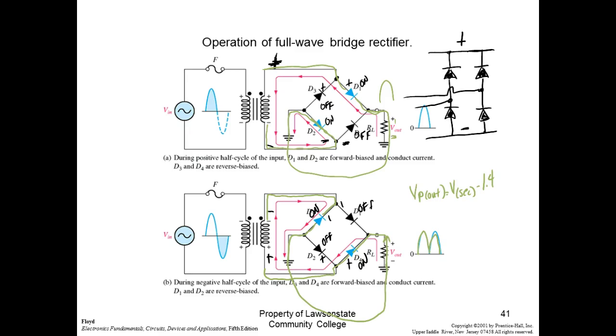So we'll also look at another power supply called a switching power supply. These are harder to build, but they're more efficient for their size. This one is rated at 20 volts at 3.25 amps, and look at the size of it. A 20 volt, 3.25 amp linear power supply would probably be about 4 times the size. We'll look at that later on. Transformers can be smaller, and we'll talk about that too.